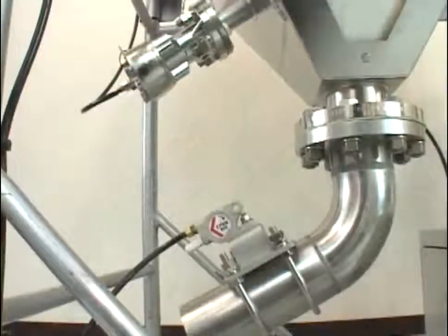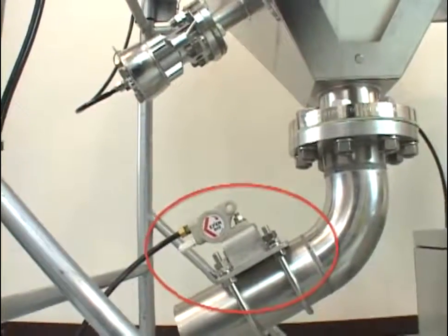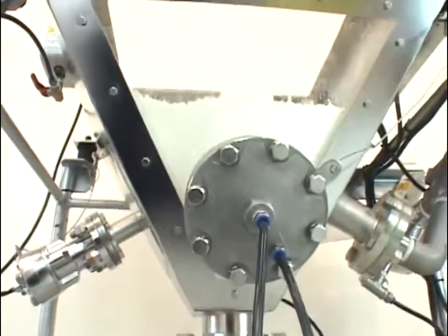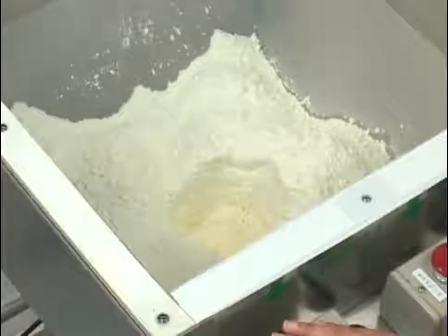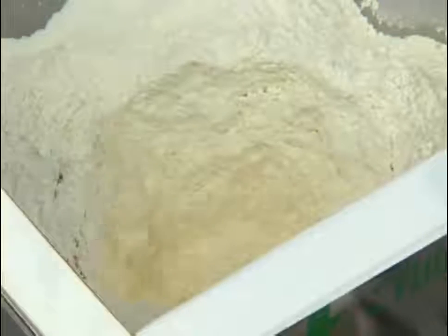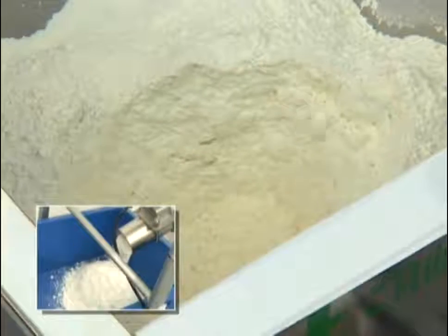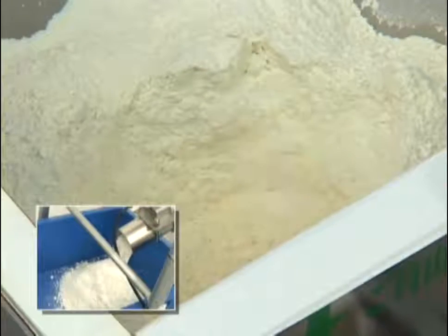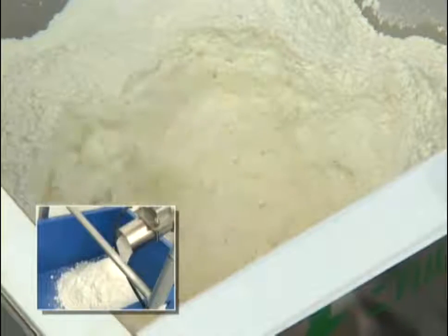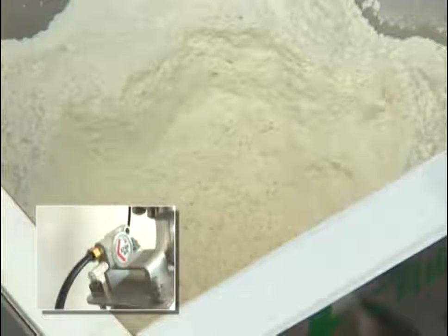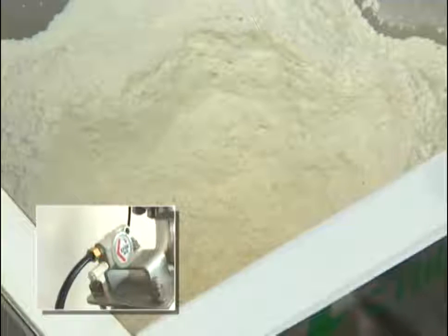Take a look at the inside of this miniature tank with a ball vibrator attached to the pipe on the experimental device. Simply by adjusting the air pressure, you can choose the optimum vibration rate and centrifugal force. And thanks to its compact size and simple construction, it's easy to maintain.